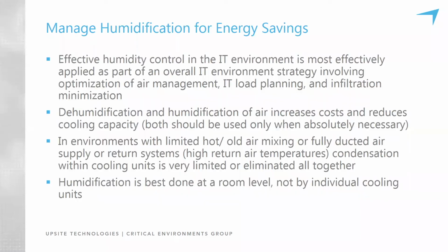Now, as I mentioned, this is a cherry-picked example. Obviously, if you go from 72 degrees Fahrenheit to 74 degrees Fahrenheit return air temperature, it won't be as dramatic because we've already gotten rid of the condensation on the coils. However, there are a lot of facilities that are operating with a small portion or a substantial portion of condensation occurring on their coils. And that's consuming a lot of energy and has the adverse effect of also removing the moisture, often requiring humidification to get that moisture back into the air. So let's talk about that a moment.